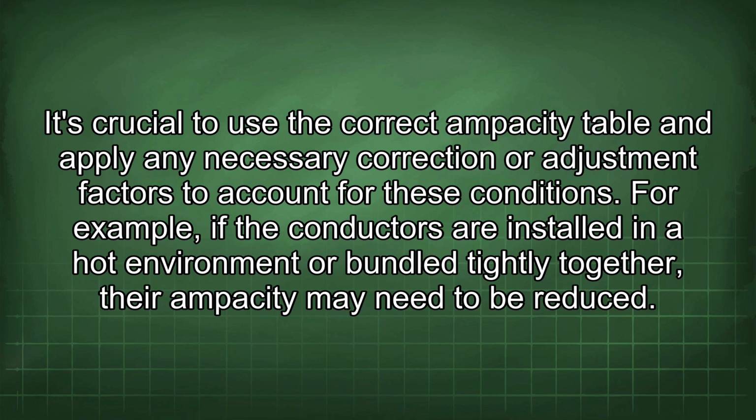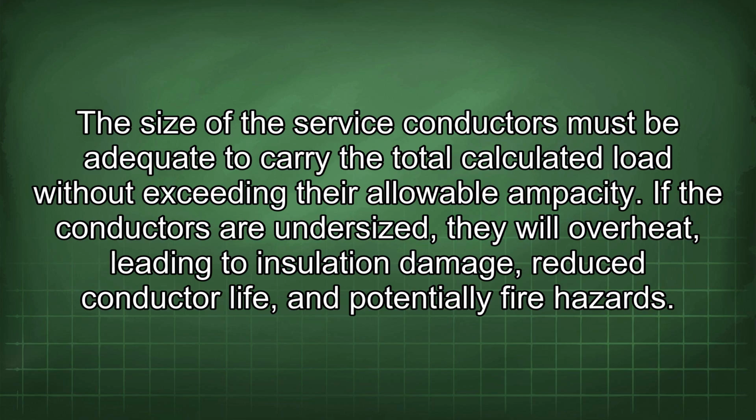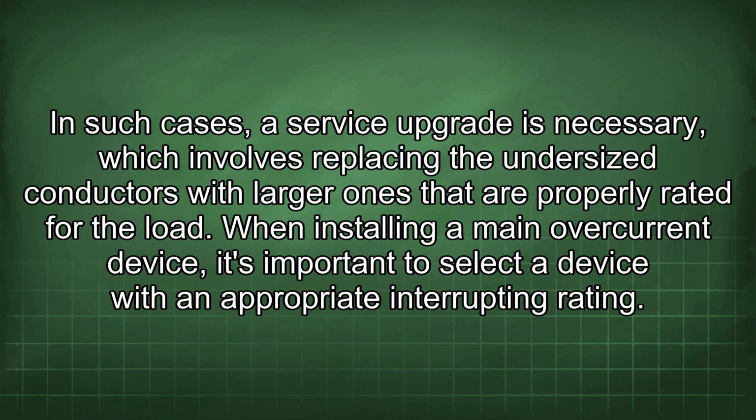to be reduced. The size of the service conductors must be adequate to carry the total calculated load without exceeding their allowable ampacity. If the conductors are undersized, they will overheat, leading to insulation damage, reduced conductor life, and potentially fire hazards. In such cases, a service upgrade is necessary, which involves replacing the undersized conductors with larger ones that are properly rated for the load.